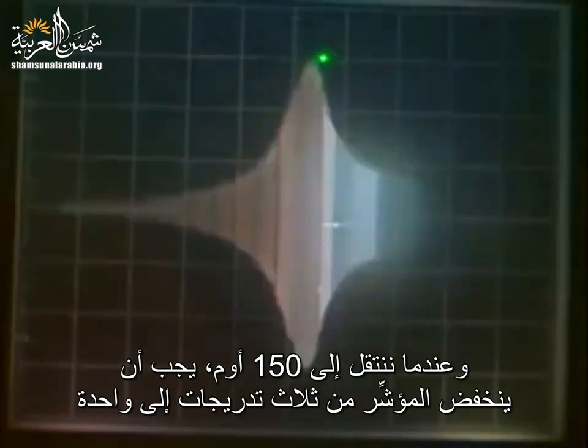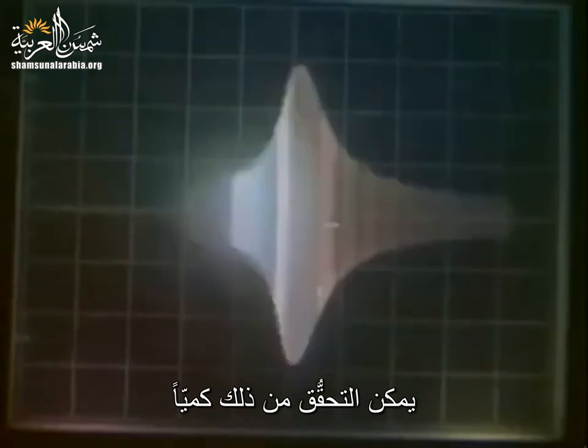Now notice on the scale here that Marcos has set the I0 at resonance at 3 scale units. So it's nice when we go from R 50 ohms to 100 ohms, it should go down by a factor of 2, and you can check that. And when we go to 150 ohms, it should go down from 3 units to 1 unit. So you can quantitatively check this, and you will see that the curve gets broader because it has a lower Q. So now I will make it 100 ohm.